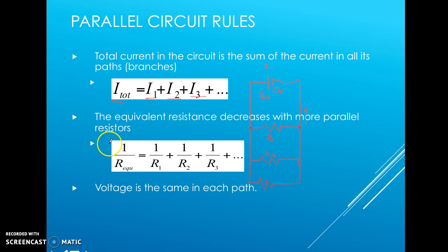One note about the equivalent resistance, to double check that, is that we are solving in this equation for 1 over the equivalent resistance. So when we do something called collapsing the circuit, which I'll show you in the next video, we are solving for 1 over equivalent resistance, so we will need to take the inverse of that to solve for the actual equivalent resistance of the circuit.